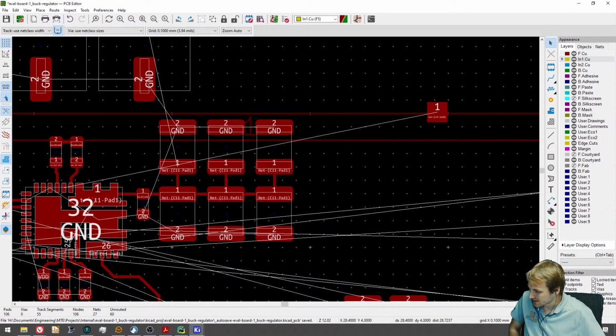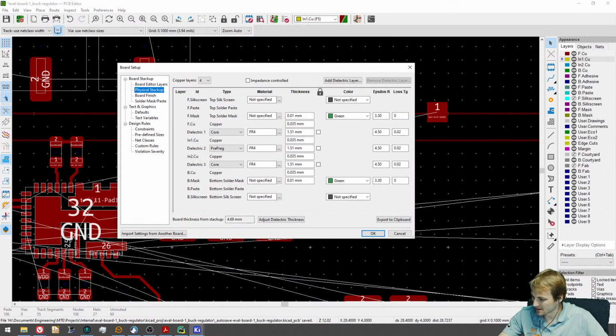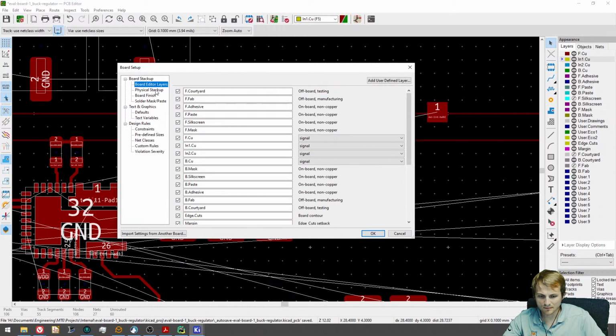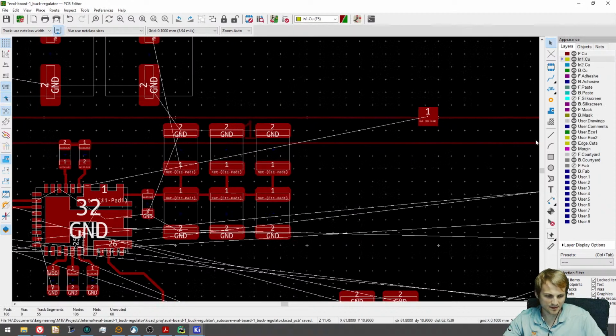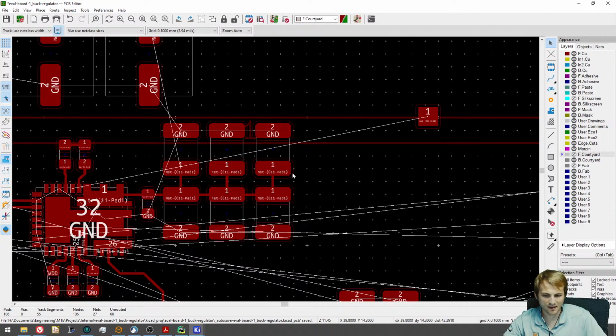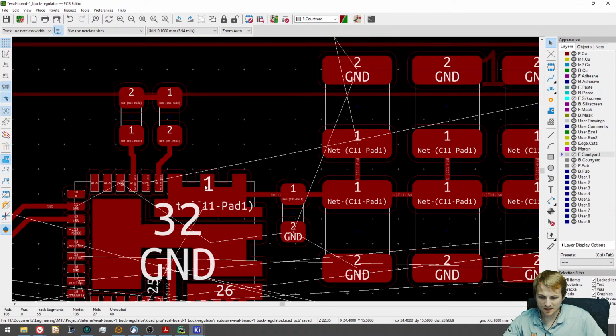Does it help to alternate the different grounds between the VDDs to help with EMC? I don't really know what you're referring to. Does it help to alternate the different grounds between the VDDs? So all of this is here. This is what I was looking for. So they still have that. All of this is just a single ground tied together. I don't have an analog ground. I've mentioned it before. More often than not, you're better off, even if they suggest otherwise, to just keep a single ground. It doesn't make sense most of the time.